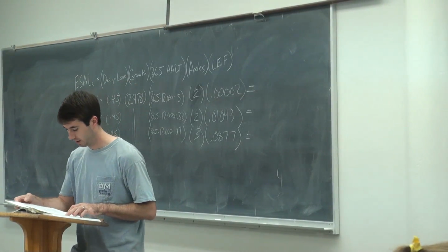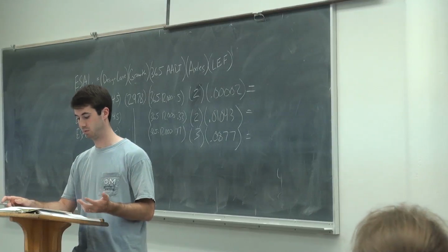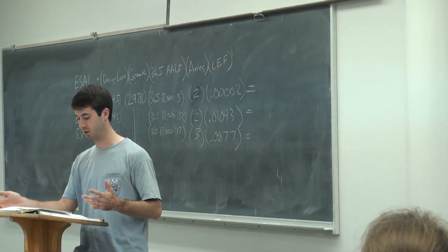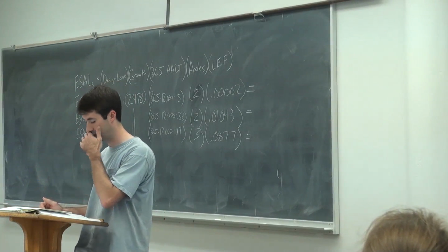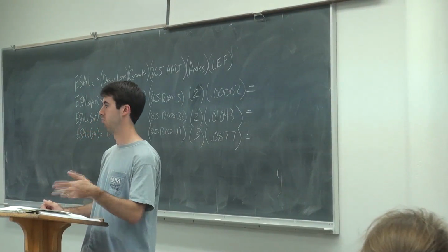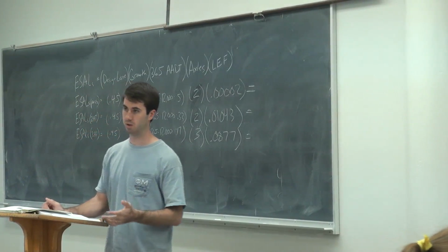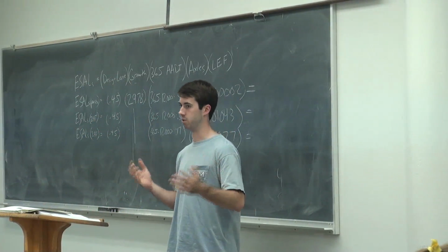You get the idea. The binder, you've got P or G, basically what percent binder you have, or what is the specific gravity of the binder. And then for P, you got PB, PE, PA, all those things. Percent binder would be, you got 5% binder in the mix.